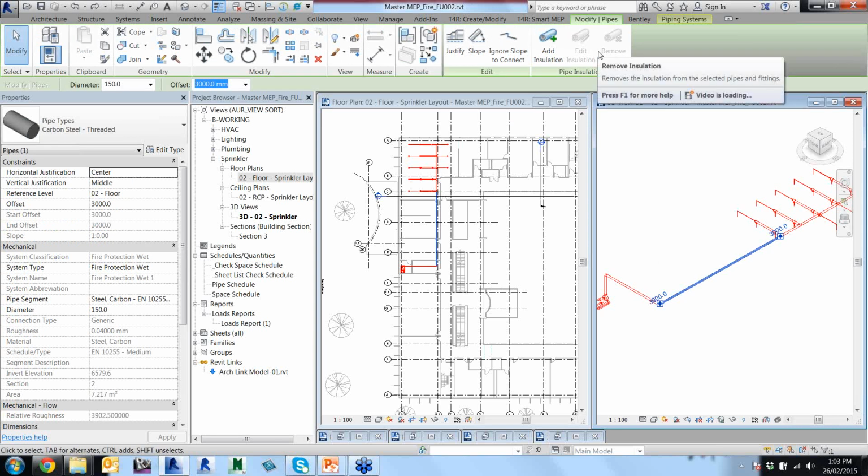the automatic size duct and pipe sizing tool that you get with duct systems and other hydraulic or wet water domestic water pipe systems. Okay, the automatic pipe sizing tool doesn't work with fire systems. The main reason the auto size tool doesn't work in Revit is that the auto pipe sizing tool has no way of selecting and calculating which heads are in the highest demand.